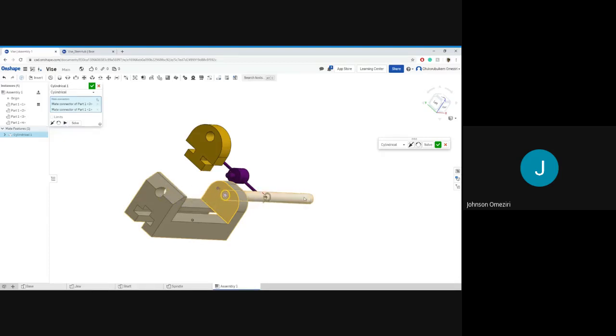This should be like a bolt that spins. If I play the animation, it shows, okay, this is what I want you to do. I want you to be a cylinder. I want you to be able to rotate, and I want you to go in and out. So that's good. Once I'm satisfied with this, I could just click the check mark here. So play to just see the animation. That's what I want you to do. And check mark here, done.